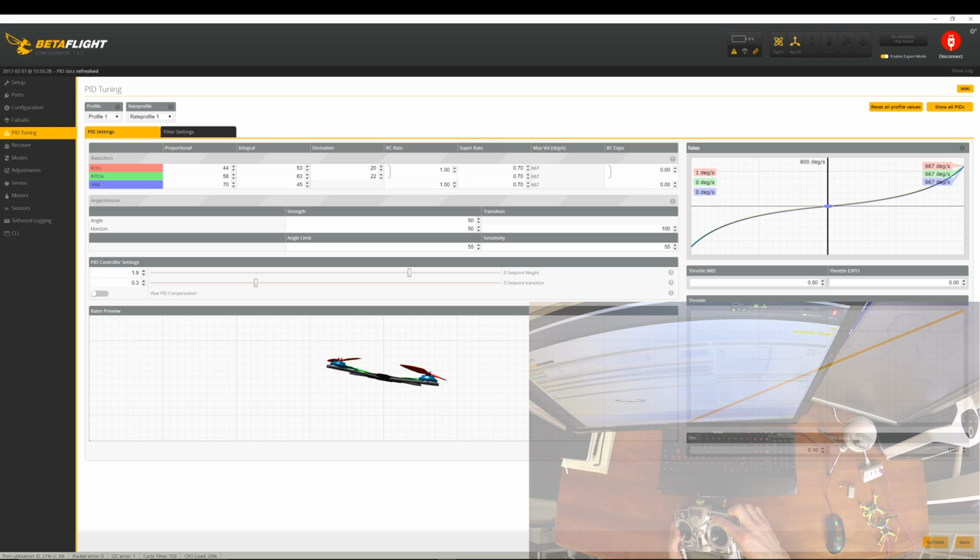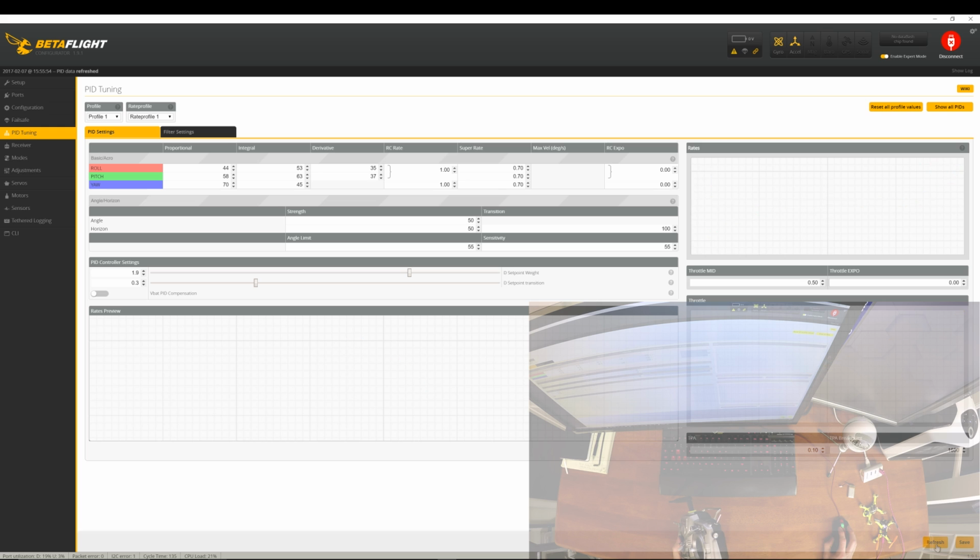Now if we wanted to increase the D value, we go into our D position and press up, and see again this blue light is flickering, showing that it's adding value. We'll go back to the detent, which is the neutral position on the switch, and it should stop adding value. So you can see here that those values increased.